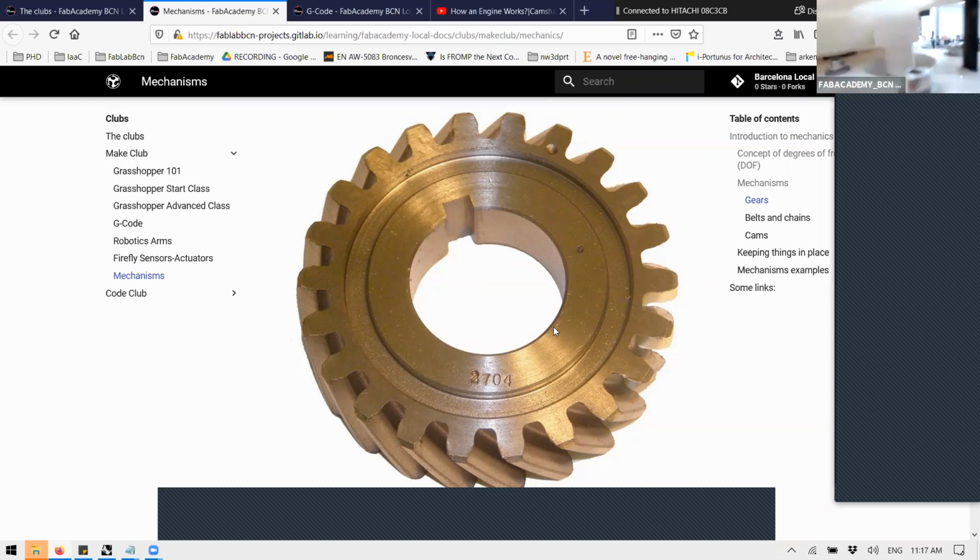That is done so that you can reduce noise and increase the amount of time that the teeth of these ones and the teeth of this one are in contact, by increasing the surface and also reducing how sudden the contact is.